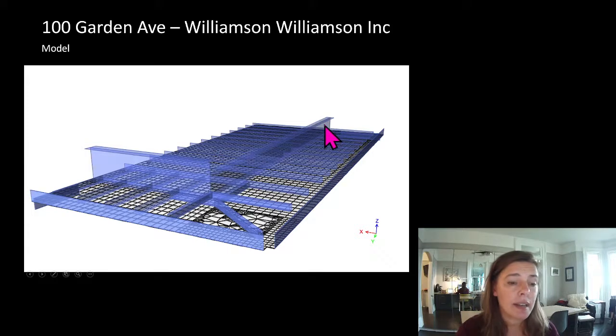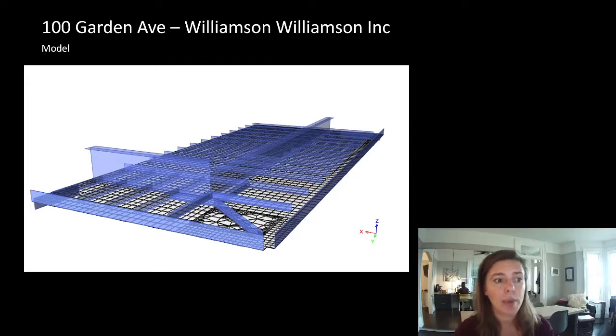Here it is, kind of. My modeling software, like I've said before, isn't great for giving extruded images, but it can help a little bit. So you can see here that I modeled in the base building structural beams as well. So what's interesting is that this beam was also cantilevering, picking up this simply supported beam. So we needed to make sure that our impact on this beam right here wasn't too great.